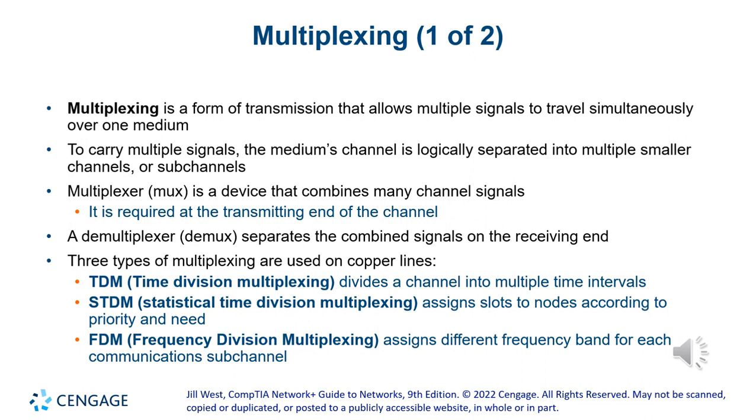Imagine if you have a light transmission and you can have multiple colors, right? Multiple colors of light. You can compress that into one signal. You get it across the wire. When it gets to the other end, you demux it, and then you get all your different colors back. So the green talks to green, the blue talks to blue, the orange talks to orange, and like that. That works because if I'm sending with a blue sender and I'm expecting to receive a blue signal, when I see green or yellow, I'm not going to listen to any of those. I'm going to listen only to the one that has a filter on, which is blue, and just receive the blue signal.